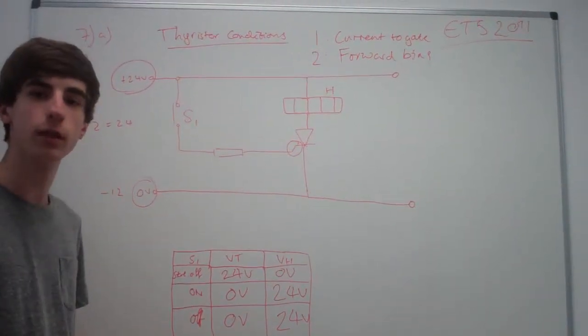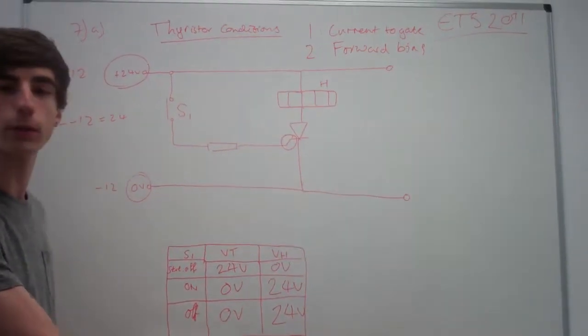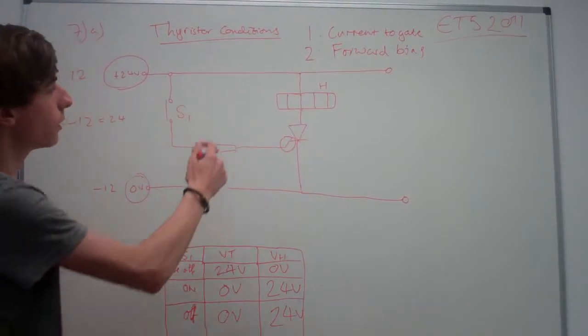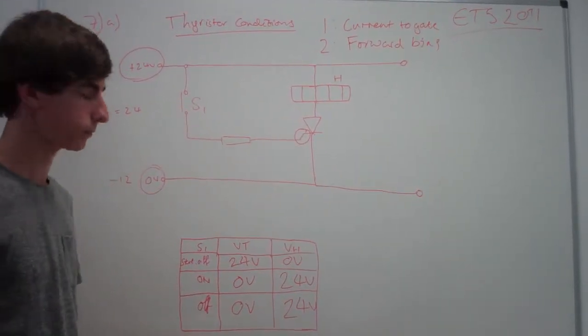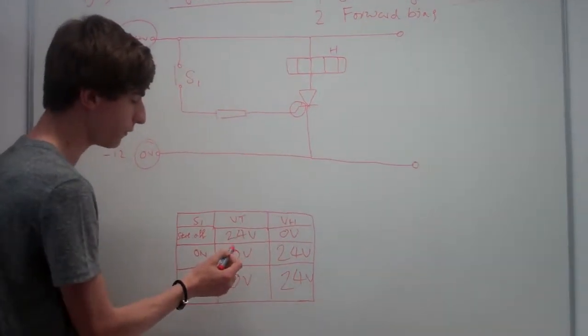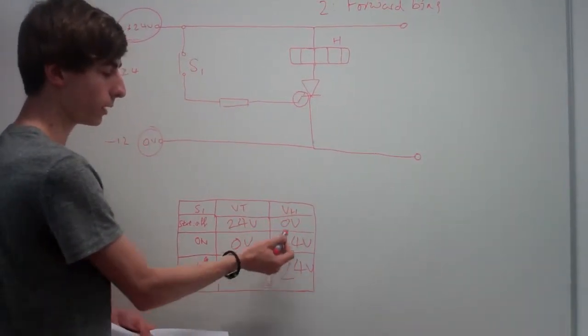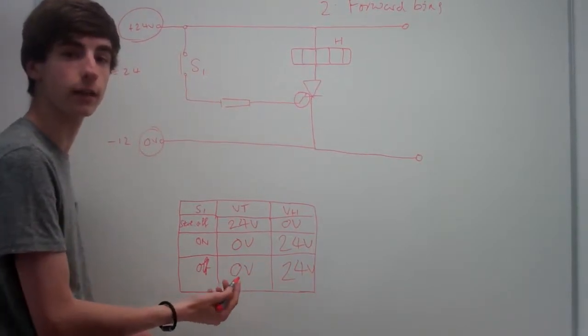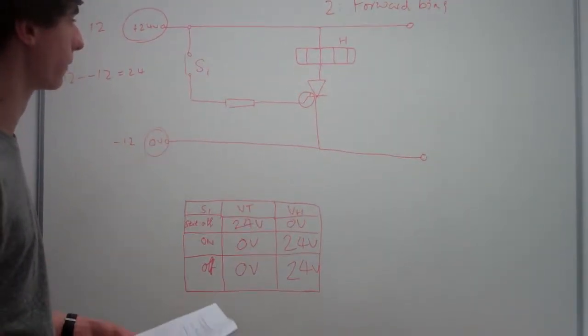You click them once and they come on. You don't have to hold the switch down. You just click it once, the pulse comes through and they go on. Nice and easy. And if you just remember this arrangement with 24 volts and then remembering it's the opposite way around across the heater, that's how I like to remember it.